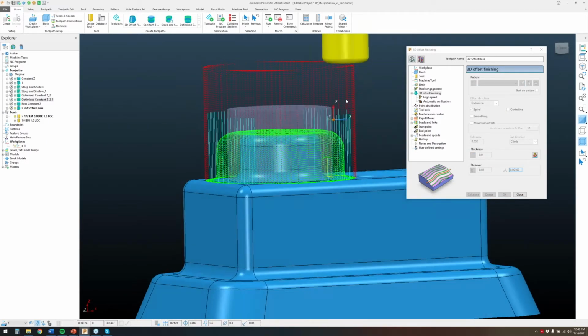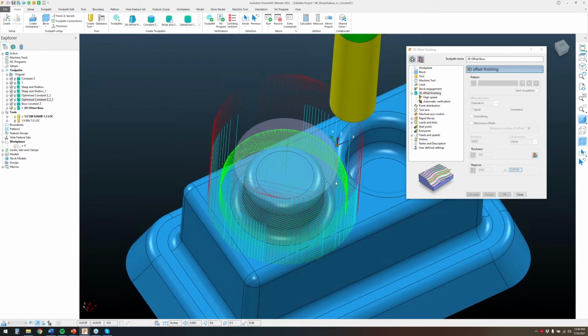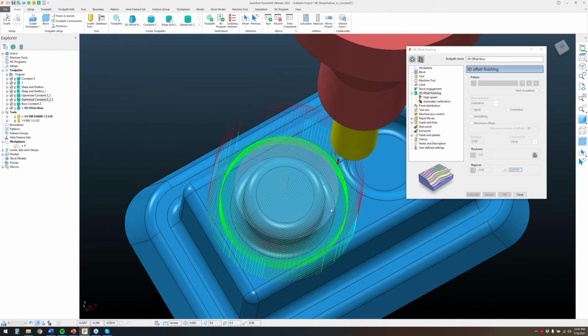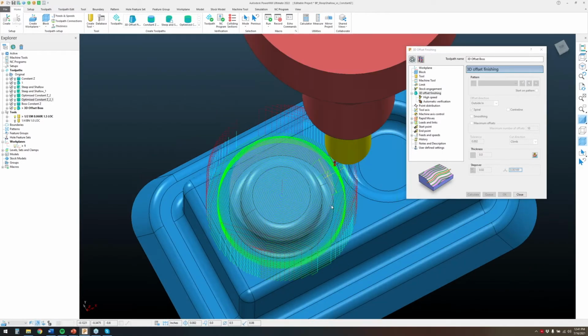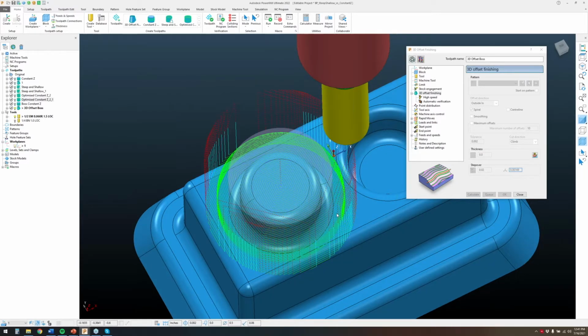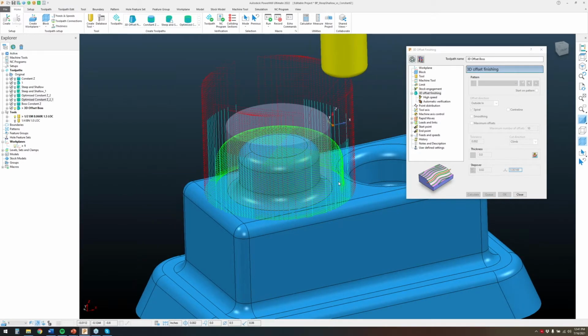Now you can see something goofy going on. If we're doing a 3D offset on here, you guys can see that it's still kind of utilizing the corners of whatever it's looking at. So it's taking a boundary and it's almost creating corners of that boundary and offsetting it. So it's not going to really look much at just the boss to say, hey, I can spiral in a nice smooth radius. It's tackling it in a way that you may not think is ideal for this specific part.